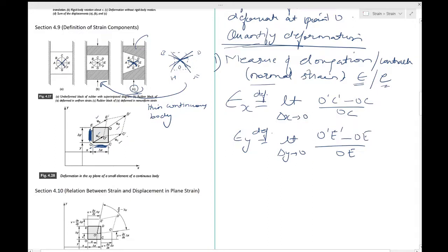with respect to its original length. Let's go with the symbol now and we'll transform at some place. So this is called a normal strain, and it is evident that the normal strain will be positive when the line has elongated, and it will be negative when the line has compressed or contracts. Now look at the second case,